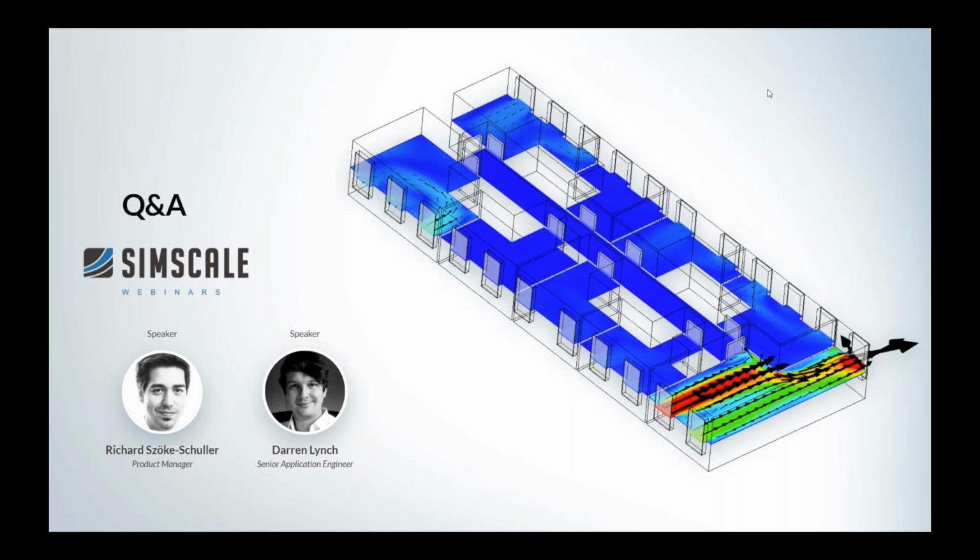This gives us a relationship between window size, window opening angle, pressure drop and flow rate. That is what we implemented in SimScale. When we get this relationship between pressure drop and flow rate automatically from our code, this is what we use to model that restriction, if you like, of the windows. I hope that answers your question. Feel free to ask any follow-up questions.